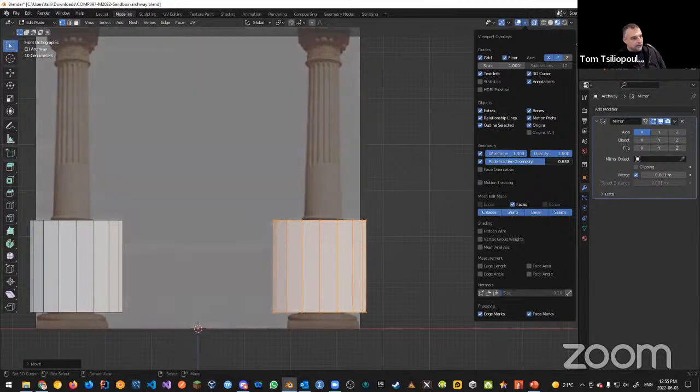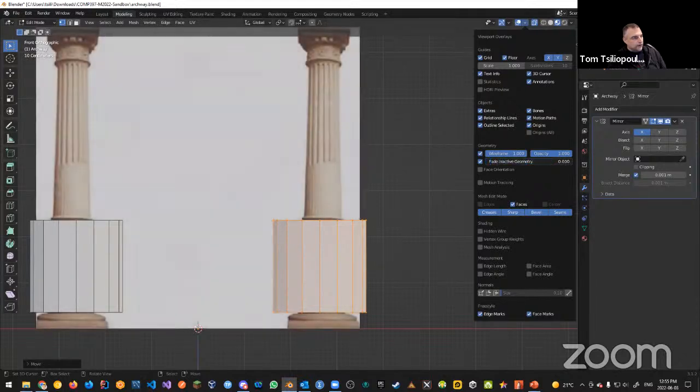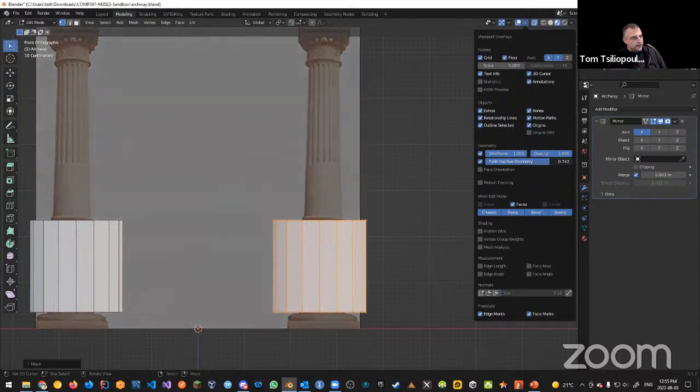So the background is basically what we're talking about. If it's inactive, I can fade it out. So it's in the background, but it's not taking up a lot of space, or I can bring it up brighter if I really want. Let's make it fade away to something like 0.7. Again, this is in the viewport overlays tool up here, okay?